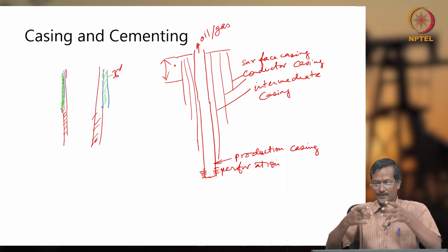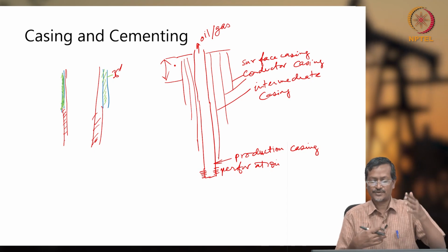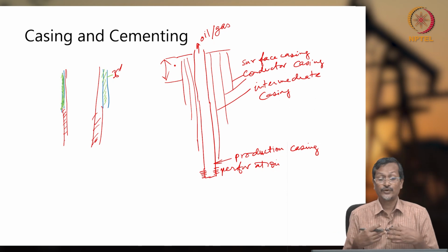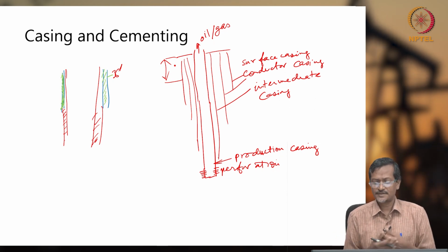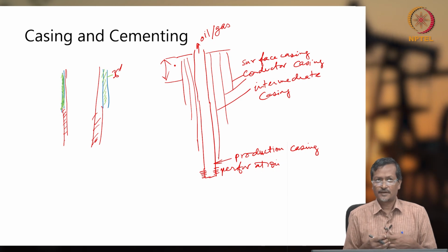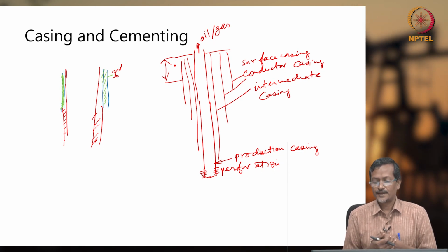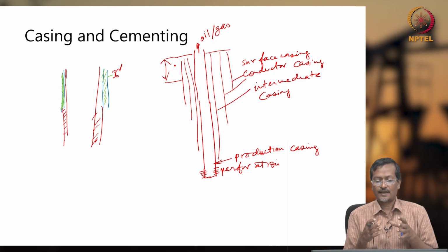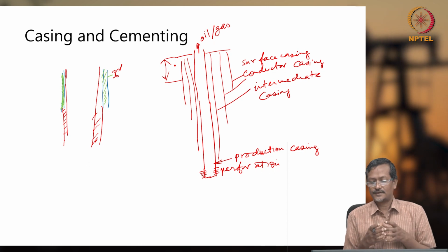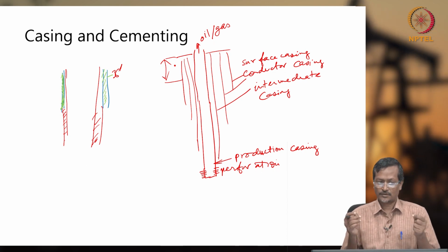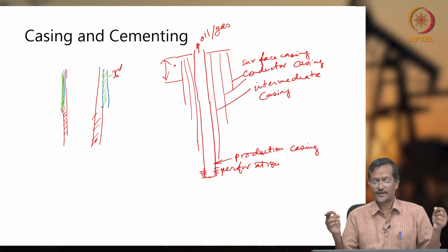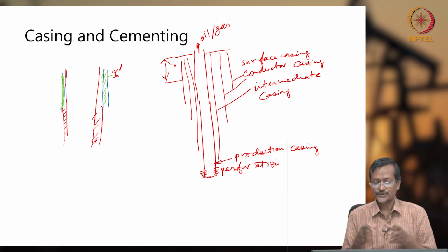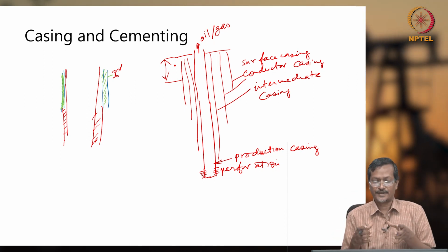And when you are drilling down after maybe 500 or 1000 feet, there will be no such issue. So in that case, maybe open hole drilling, sometimes we do open hole completion, so no cementing will be there. Sometimes it will be cased hole completion, sometimes a sand control system will be there. So those cementing systems are to make the hole stable and safer, and also so that wellbore reservoir fluid should not enter into the pipe, or piping fluid should not go into the reservoir, that also it will ensure. So that's why there will be several levels of metal pipe and cementing options.